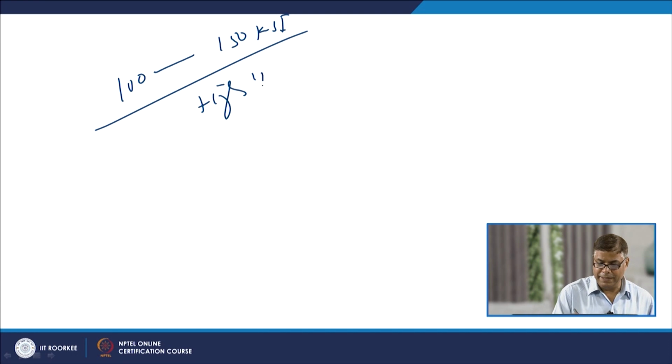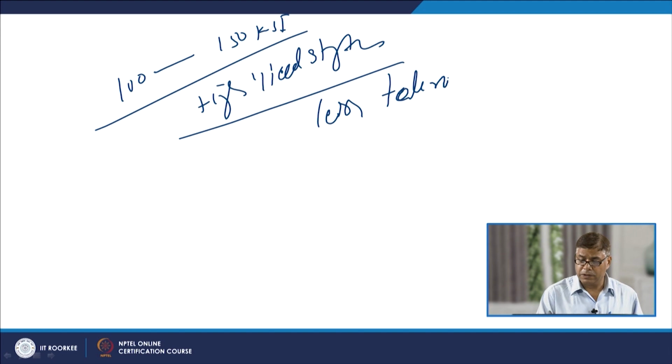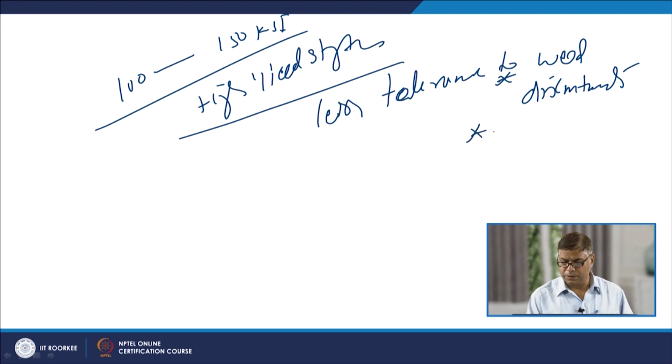Since these steels are normally of high strength, like 100 to 150 KSI, because of the high yield strength of these steels, their weld joints are less tolerant to weld discontinuities, because these easily provide high stress concentration to promote the crack growth rate and premature failure.